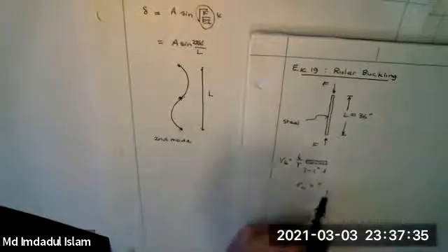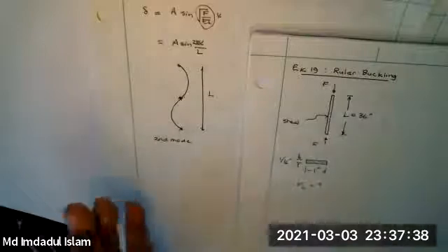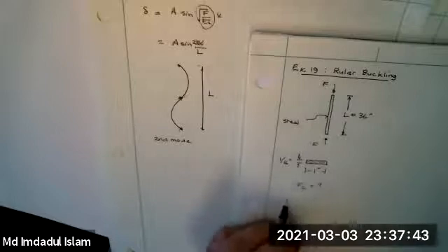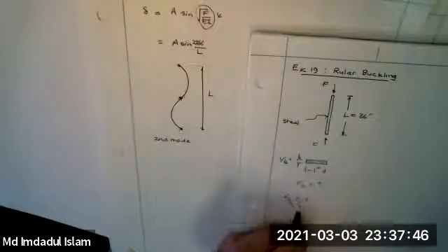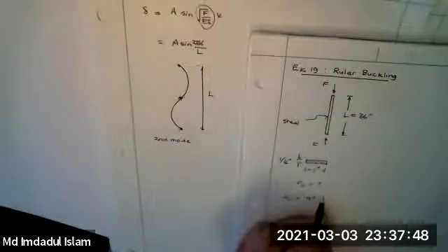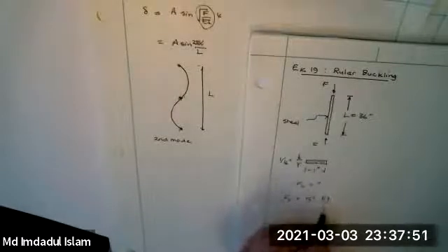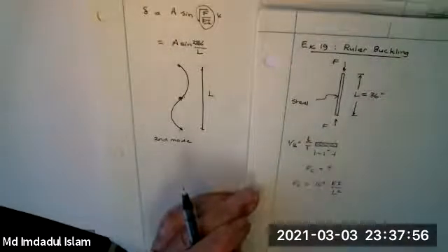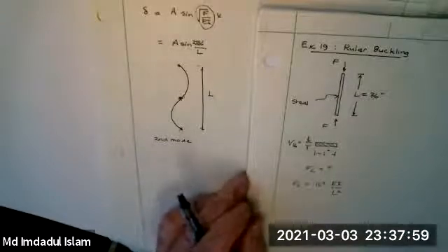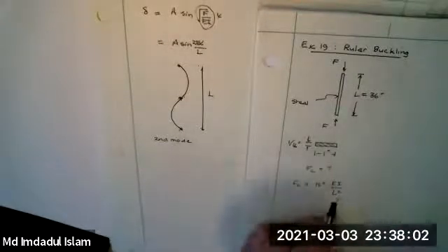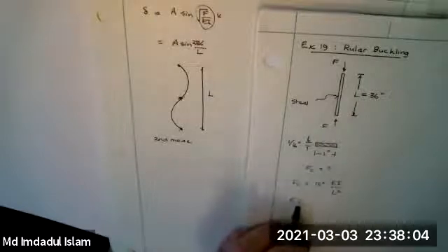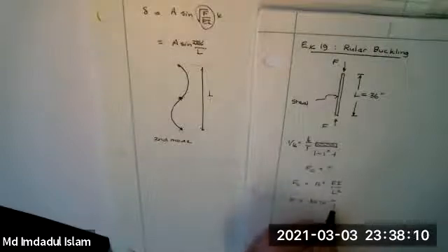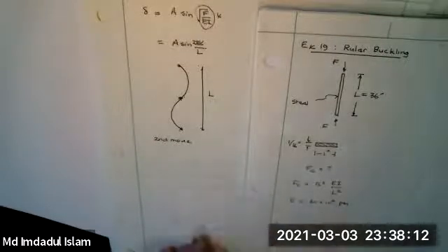So this FC, I'm going to hold this just like I held the short ruler in my hands, so it's free to rotate at the end. So it's simply supported. FC, according to the derivation we just did, would be pi squared EI upon L squared. I would have done the plastic ruler, but I had no idea what that plastic was and what the E was. Here with the steel, I know that E, within a few percent, is 30 times 10 to the 6 PSI.